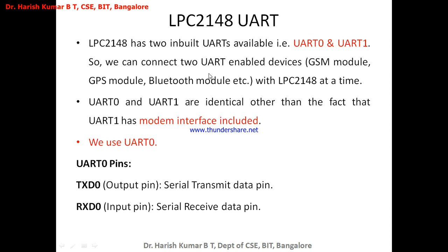So we can connect 2 UART enabled devices at a time to LPC 2148. If I want to connect UART enabled devices to the LPC 2148, how many such devices can I connect? I can connect 2 such devices at a time, because it has 2 built-in UARTs available. UART 0 and UART 1 are identical to one another, so they're the same.